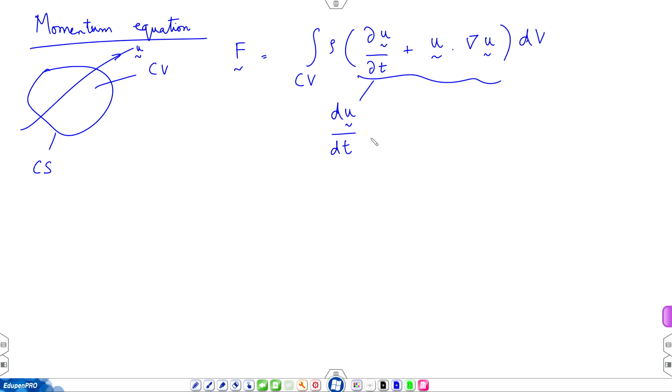So, total derivative of u with time, as the fluid particle moves from one point to another along its flow path, that is du dt, d being this letter d, while the expression in terms of partial, the two are equivalent. What is this form called? Du dt is called the Lagrangian form of acceleration. So, I hope you recall these terms from our previous discussion.